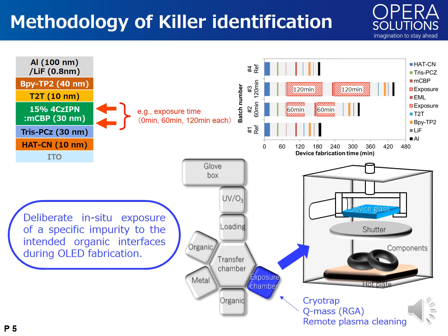If you want the second intentional exposure, just repeat the same procedure after the emission layer is done. Finally, the OLED is returned to the organic chamber to complete the remaining organic steps. Then after the fabrication, you do analysis of the OLED lifetime by comparison with a non-exposure reference.